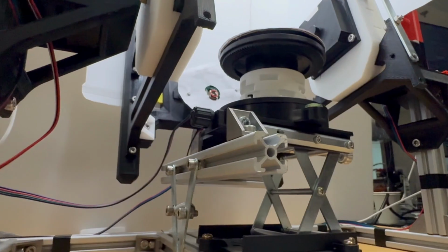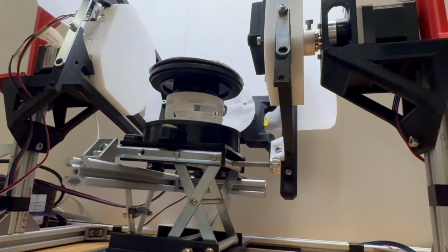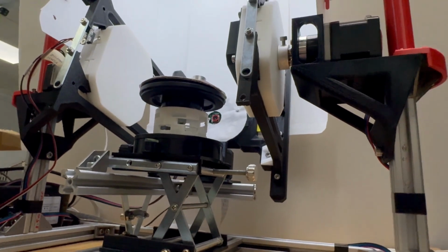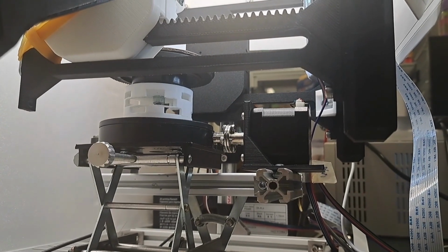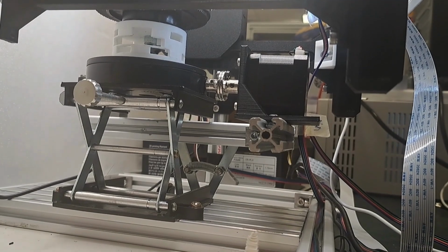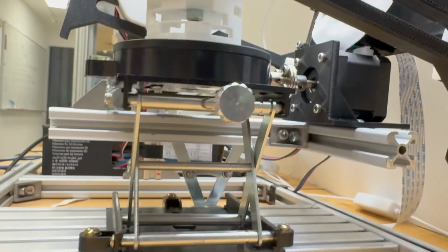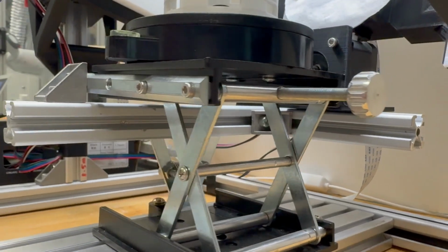To get pictures from the different azimuthal angles, we use a stepper motor to drive a bevel gear housed in here, which turns the stage by approximately 15 degrees, followed by a short delay for the camera to focus on the object and take a photo. This is iterated until 24 photos of the object are taken at unique angles.